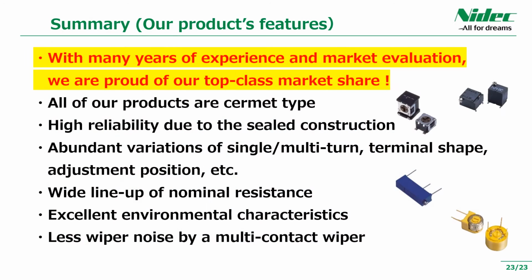Please see the summary at the end. The biggest feature is that it has been evaluated by the market for many years and has a top-class market share. In addition, all of our trimmer potentiometers are cermet type, and they have sealed structures and are highly reliable. There are a wide variety of products, and you can select the most optimum product by selecting the rotation speed, size, terminal shape, and so on in accordance with the intended use. There is a wide range of nominal resistance values and each has excellent environmental characteristics. We have also taken measures to reduce wiper noise.